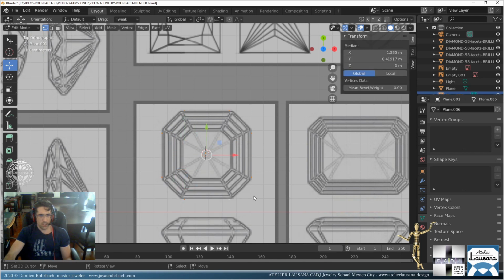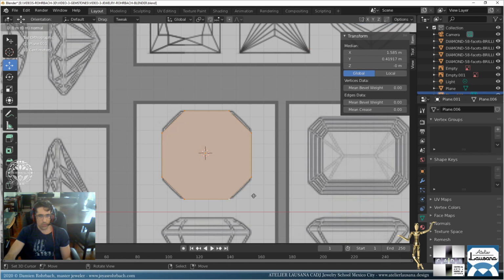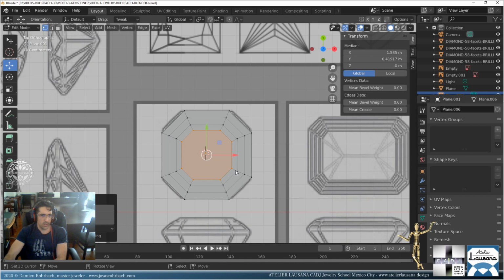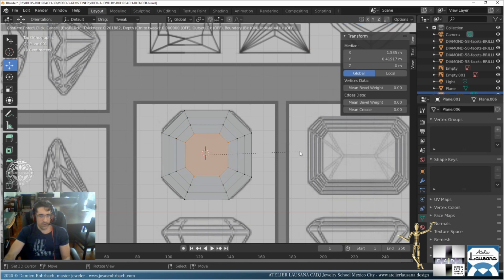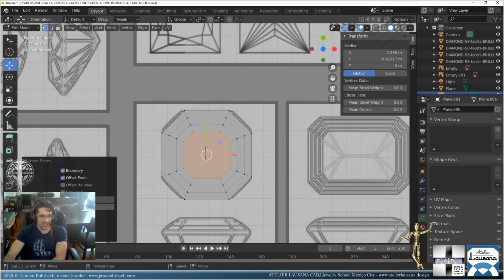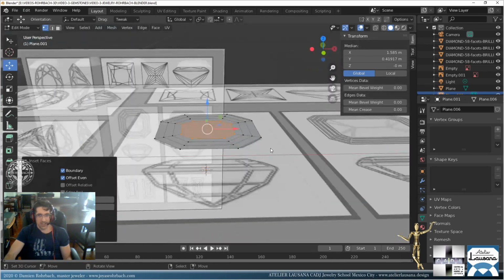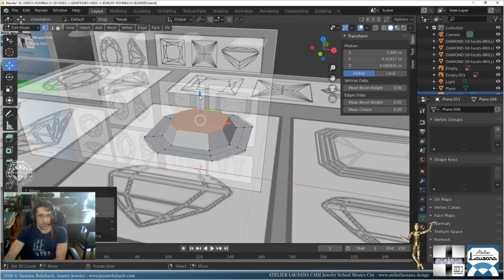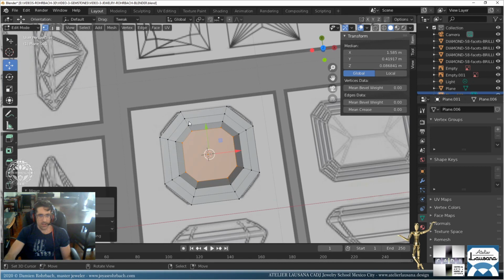This is already the main shape. Now we have 3 levels. So E, well, we can do the Y key, which is the inset key. Let's put a thickness of 0.15. Let's put 0.16. Let's do it again, and always put the same amount, 0.16, and once more. Sorry, not Y, not the E key. The I key, not Y, nor U, nor J, the I key. Okay. Now this goes up, this goes up, up.